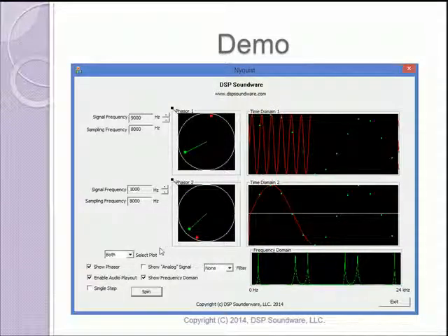So that's a justification for the sampling theorem, in that if you try to sample a signal whose bandwidth is greater than half the sampling rate, you really don't know what you have. In other words, you've lost information. So I think what we've done here is shown a reverse proof almost.